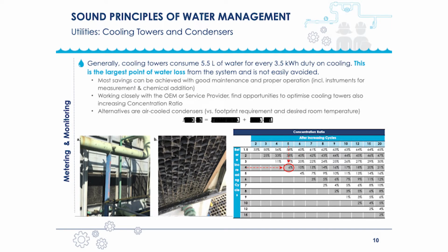Thank you. Now, let me try to be a little bit more detailed on this one. Here we're looking at the cooling tower, and you will immediately see that this cooling tower is not actually well taken care of, as there are solids accumulating on the panels, and that will allow the water quality to deteriorate.